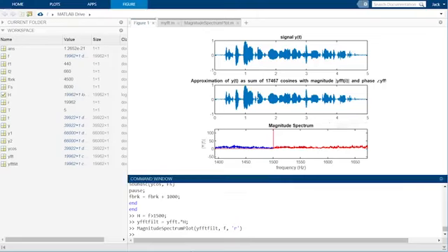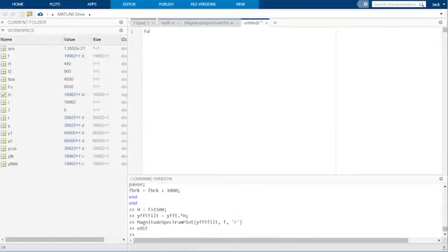So, how would we reconstruct this high-pass filtered signal? Well, we could use a for loop, as we did above, and sum together all the cosines one by one, but this is really inefficient. It is much faster to use MATLAB's IFFT function, or inverse fast Fourier transform function, to inverse the frequency domain representation back to a time domain representation. We'll create a myFFT function.